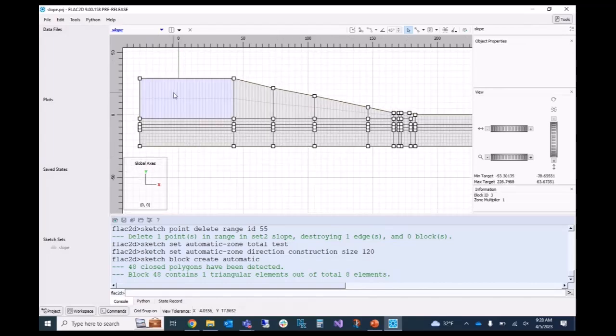And so now you have something that is not exactly what you wanted. You have a nice structured mesh, but you've only got 2 zones in the vertical direction here, which is kind of wacky, right? If you pulled it to be an unstructured mesh, that wouldn't happen. You would just get a full number of zones, and that would probably be fine. And we could do that, but just to illustrate the concept.